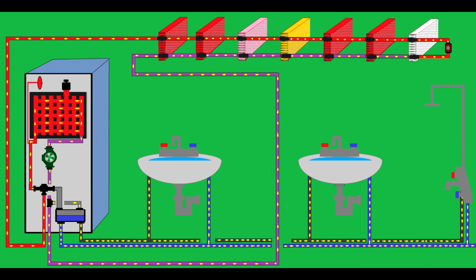In the next video I will explain to you how to make a difference between a boiler fault, or if the heating agent is not correctly circulated, or the installation is not correctly sized. As you will see, we have 7 radiators. The last one and numbers 3 and 4 are not properly heated, so you cannot assume that you have a problem with the heating agent circulation. In this case, you have blocked thermostatic valves, or maybe the valve is blocked, or maybe the radiator is clogged.